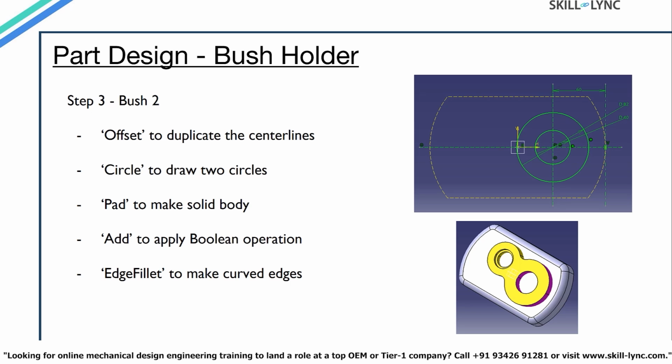I will now start building bush 2. Let's look at the slide to see the sketch and how the body output looks like. For this step, we shall use the commands offset, circle, pad, add, edge fillet and insert in a new body.